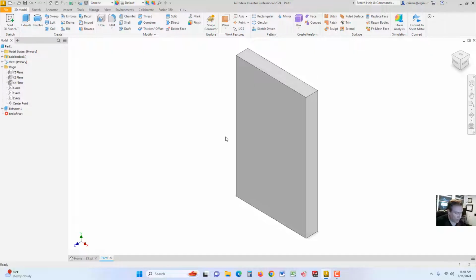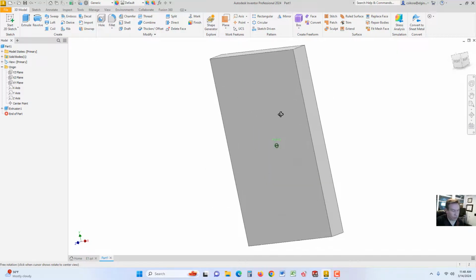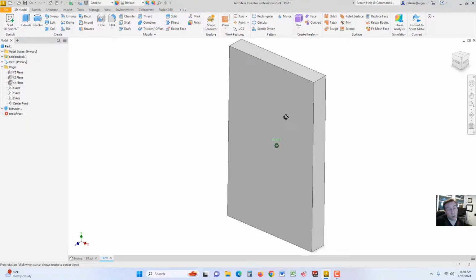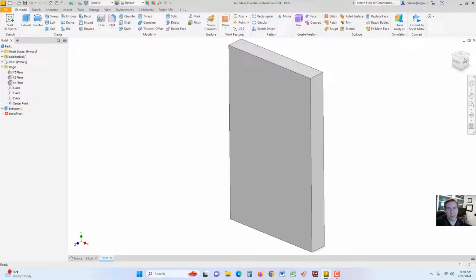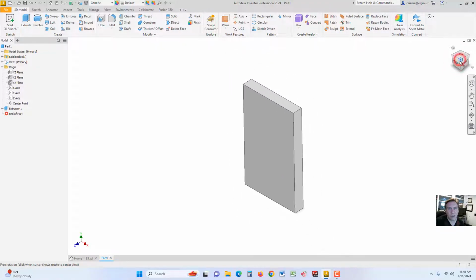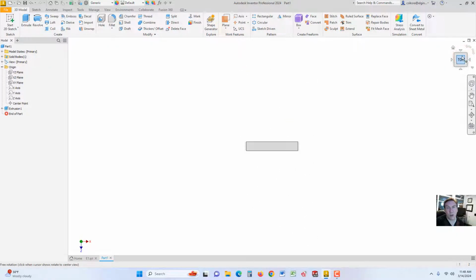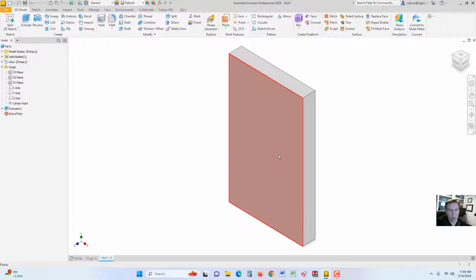Now, if you hold the shift button down on your keyboard, don't let go, hold it down, and move your pointer over the surface. Now, on your mouse, there's a wheel. Most of them have a wheel or they have a third mouse button. If you scroll, it's zoom in and out. But if you push it down like it's a button, and then move your mouse left, right, up and down, and remember, you're holding shift, this is how you dynamically rotate. So that's one way. So you could pivot, as they call it. And over here in the upper right, you could also click on a face and drag it, and you get a little bit of movement there. It's kind of quirky, but you could also click on corners of the box or click on the home button again, or click on top or front or right if you want to go to that specific view orientation. There's also these two little arrows here in the upper right. This is for clockwise and counterclockwise rotation. But let's go back to the home button. So there you've learned a little bit about how to rotate.